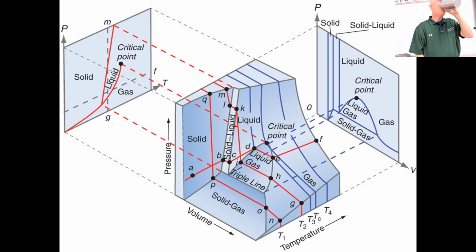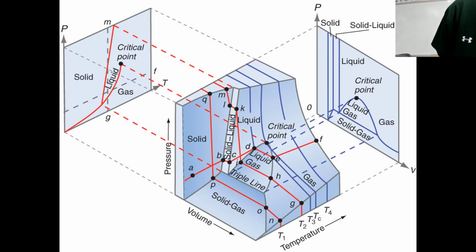There is a steep increase in pressure because you're all liquid, moving toward the solid liquid line, so pressure is increasing dramatically. It's difficult to compress. Yeah, so you're compressing, so you're still pushing on that piston. Volume's changing. The volume's changing. Yeah. Slight change, you need more pressure. So the rise over run is that slope, very small run, very small change in volume creates a huge change in pressure. So you have a dramatically steep curve there.